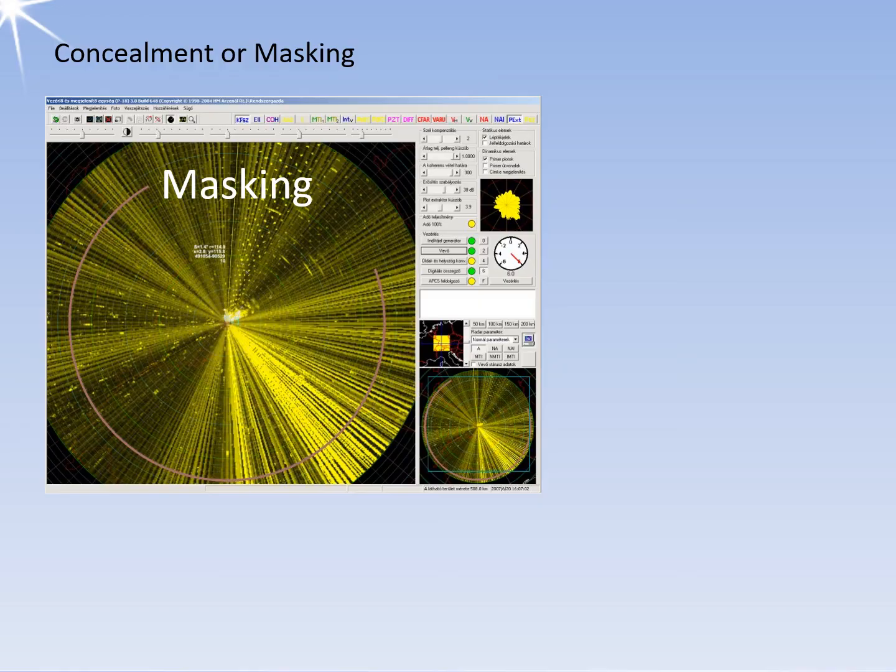The figures illustrate a radar plan position indicator, PPI, scope screen with a return signal and noise cover jamming that is strong enough to hide the return. In an ideal scenario, the jamming should be powerful enough to make it impossible for a trained operator to detect the signal presence. However, if it is not practical to achieve that level of jamming power, reducing the SNR level is sufficient to prevent automatic tracking. Automatic processing requires a better SNR than what is required for a trained operator to manually detect and track a signal.